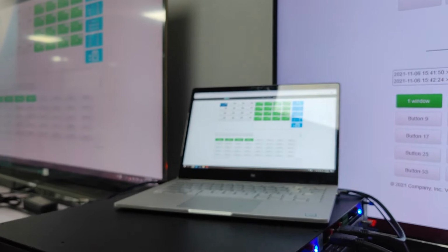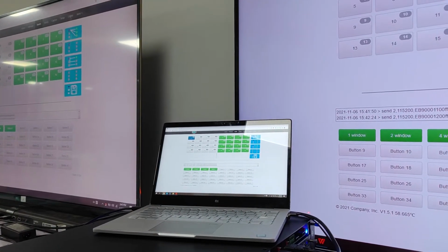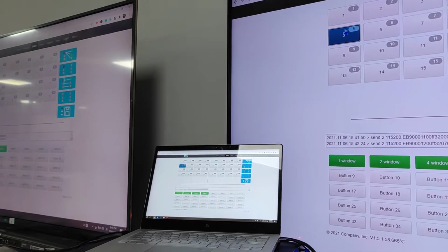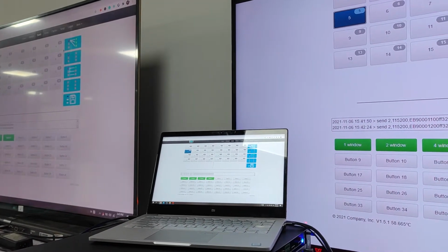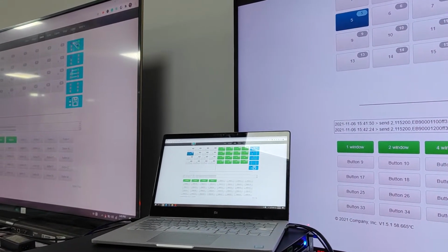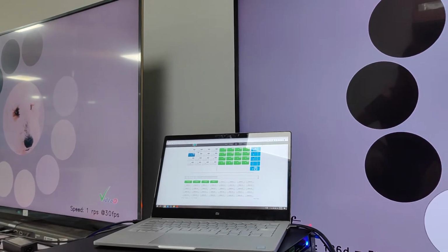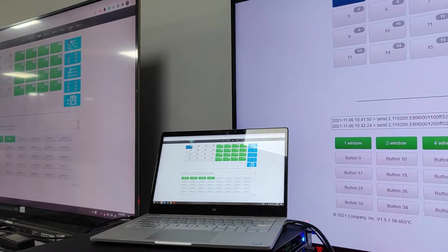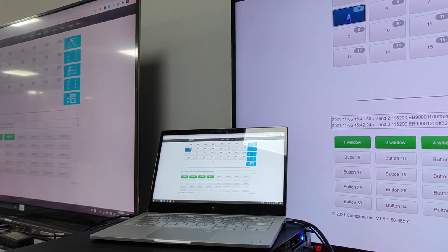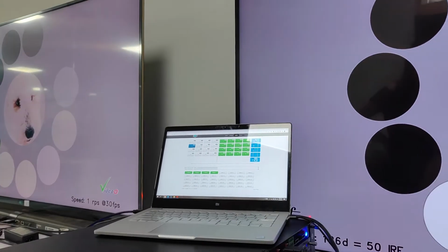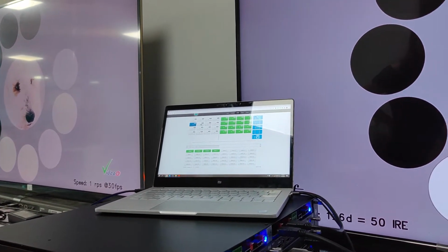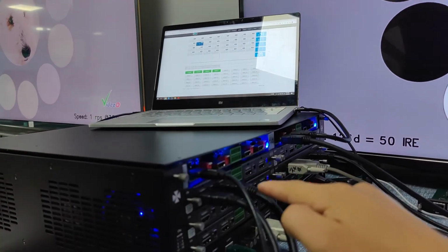So now we have input 1 switched to audio TV, and input 5, which we did the DIP switching setting on the card, switched to audio outputs. As you can see, it's actually seamless switching. We switch back to input 1 again, 1080p, and switch back to the 4K60. It's seamless switching, but input 6, which we haven't done the DIP switching setting on yet for this card.